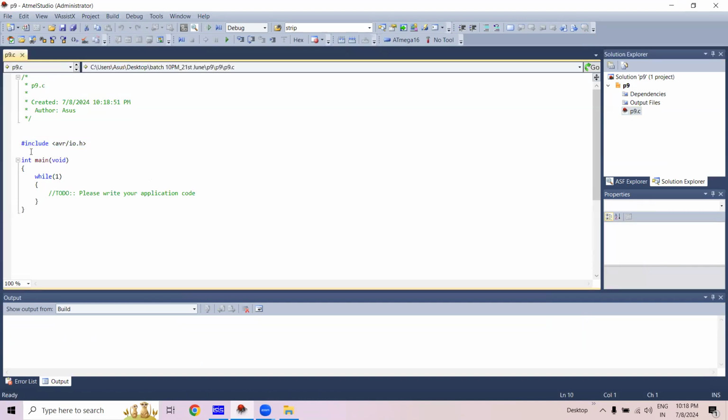Okay, so this time we don't need this delay function because now we are not asking the motor to rotate clockwise and anti-clockwise back to back. Because now we have control through buttons. So we will be turning on the button to keep the motor clockwise, and turning off the button, or another button, for anti-clockwise. For now, for this program, I'm only considering one direction, which is clockwise. Another one is the stop process.